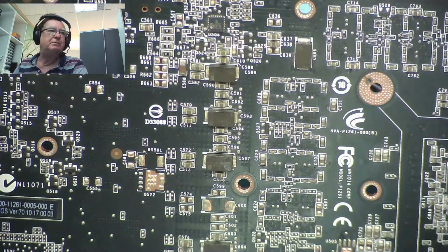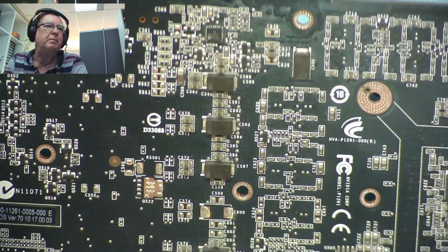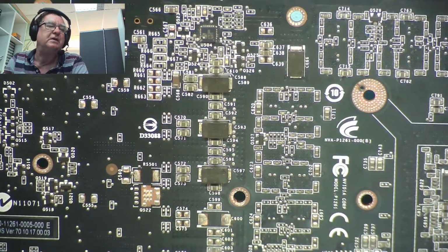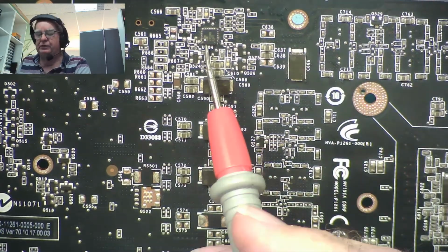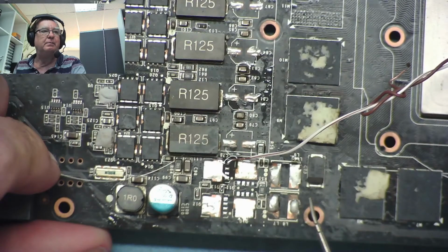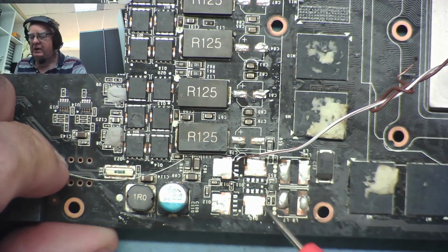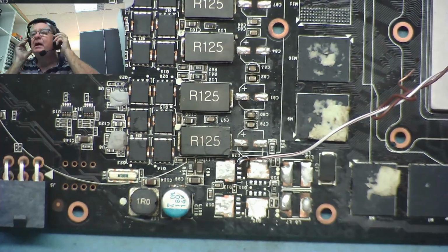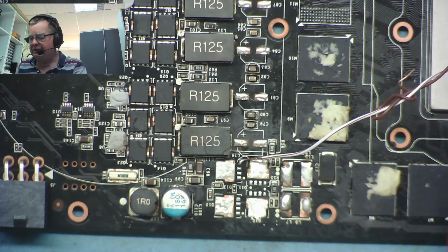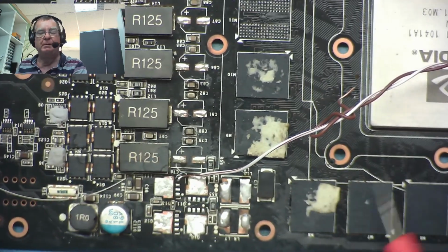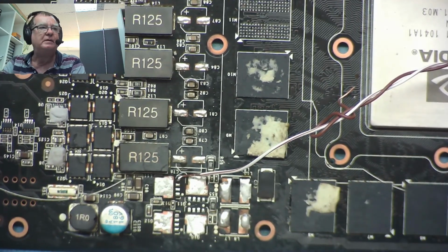Okay, so that's the last bit of the jigsaw. The resistor can go back on, I'm sure it was a resistor now. We need to change this chip. We need to change the two high side MOSFETs, which were short to the gate. We'll change the two low sides at the same time, and we'll cross our fingers and hope it hasn't damaged the GPU or the RAM. But now there's only one way to find out.